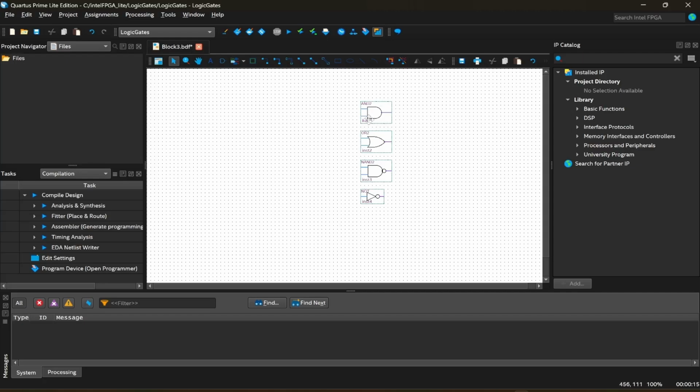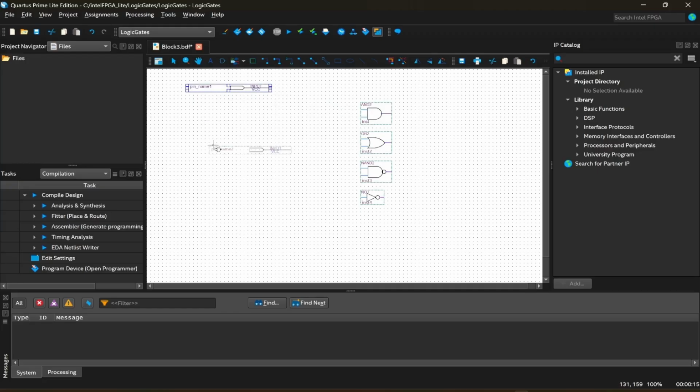So now we need some input ports. So in this here, you can select the drop down, you can pull inputs and outputs. So let's have some inputs. Let me place it here. Since each gate, some of the AND, OR, and an NAND, it has 2 inputs, so we need 2 input ports. You can click the escape now. We can align them.